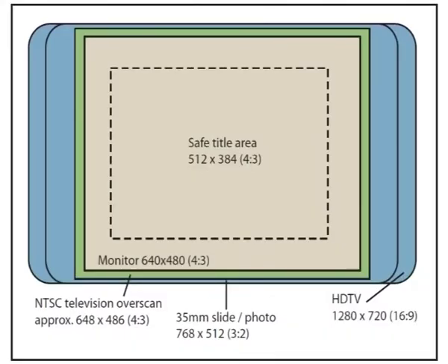Consequently, when a digitized video image is displayed on a CRT, there is a border around the image, and when a computer screen is converted to video, the outer edge of the image will not fit on a TV screen. Only about 360 of the 480 lines of the computer screen will be visible. Video editing software often will show you the safe area while you are editing, as shown.